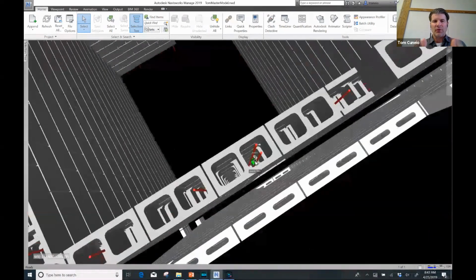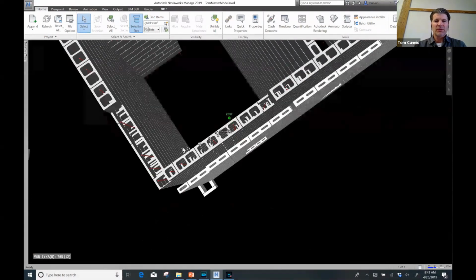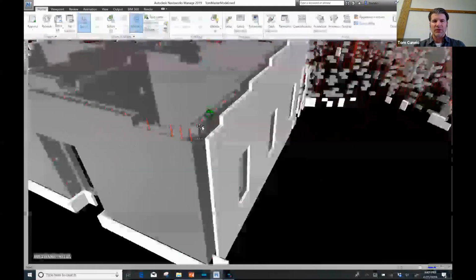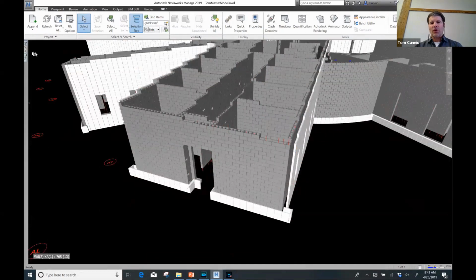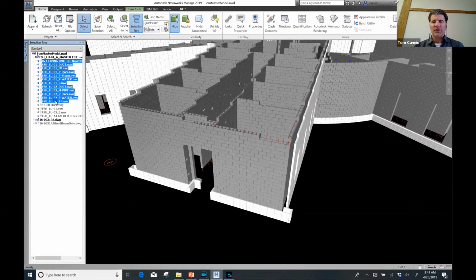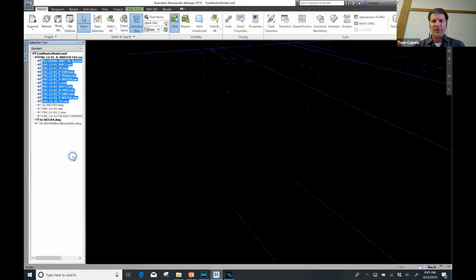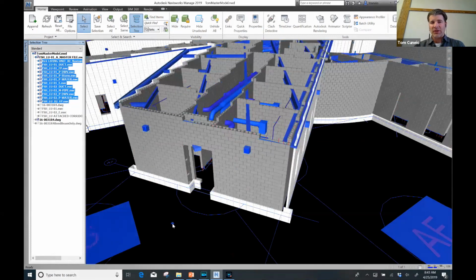You can see we've got vertical rebar. So this is our tensile load resistance in a masonry wall. So the rebar schedule from the structural engineer has been actually modeled and imposed into this world. And we're using these models, again, very effectively for production orders, for figuring out pieces and parts accurately, and then for doing clash detection and coordination.